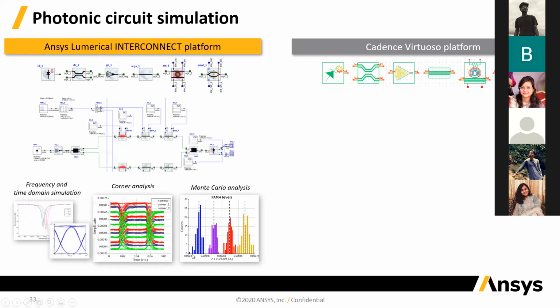By these histograms, you can see that if you fabricate this circuit multiple times, these levels will vary from one circuit to another. What's critical is that even if there's variation in those levels, as long as they're spaced away from each other, you'll still be able to identify all 4 levels and your circuit will work. So that's the requirement here: you do a statistical simulation, figure out the variations you see between all those fabrications, and make sure that everything will work with those variations included.